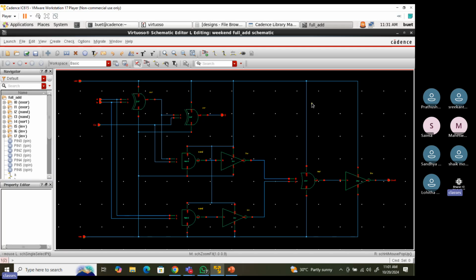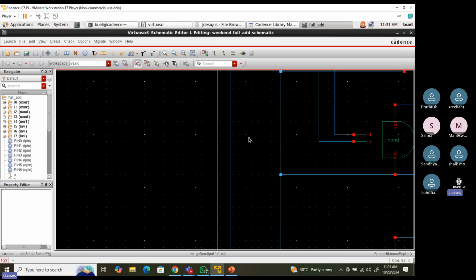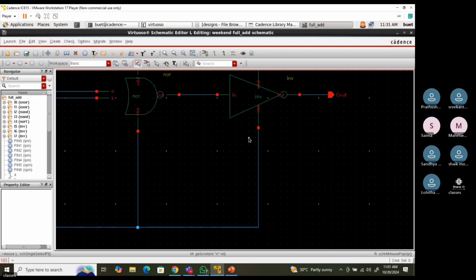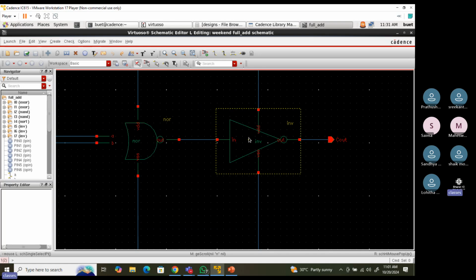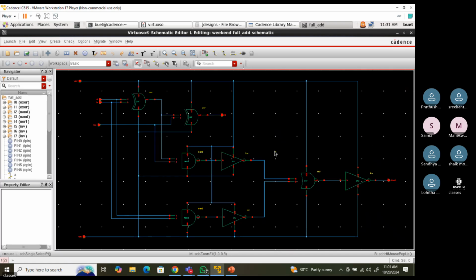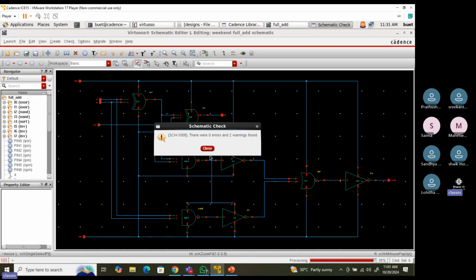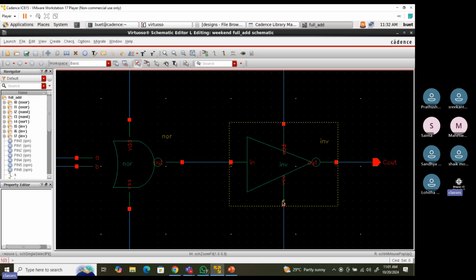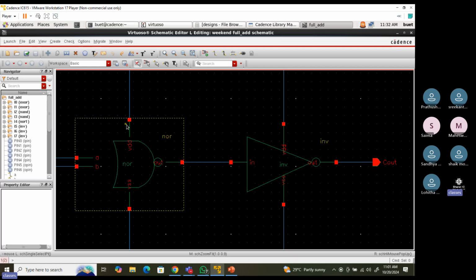It should be passing this warning thing. So where the warning is coming, we need to check that once. So somewhere I think some warnings are coming. Let me check these warnings, where this should be coming. Might be some checks we are unable to pass. I think it is coming somewhere from this part, right? I think it is coming from this NOR gate itself only. Because earlier this NOR gate had that issue actually of the extraction issue.